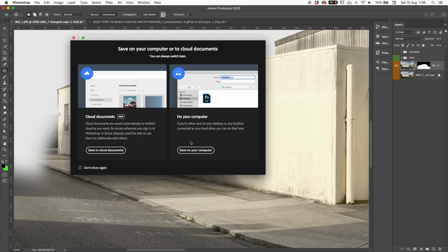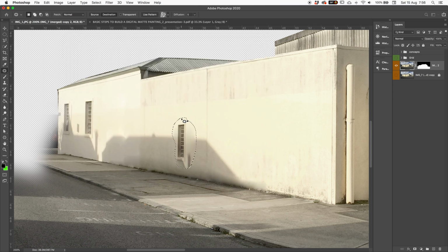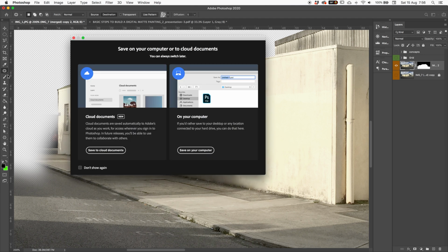And this is why it's important to be aware that this is slightly different to the stamp tool, because it looks at the background. And sorry, I keep pressing the wrong key. That's what happens when you switch between PC and Mac quite often. So let's undo that. So if I drag this over like this corrugated area here, you can see now it's picking up the grey of the corrugated area. So it's trying to fix it up, going, you want this texture over this area. So that's the patch tool.